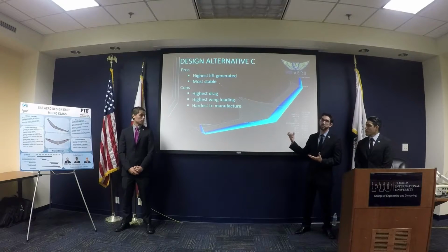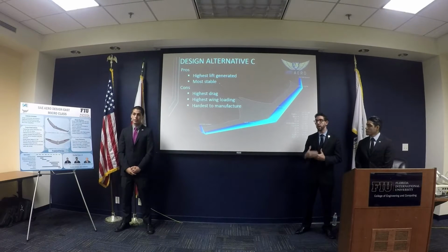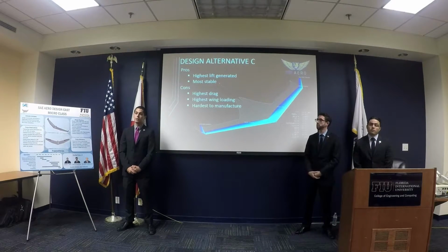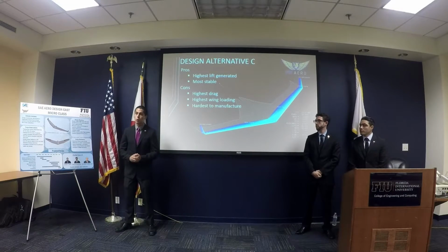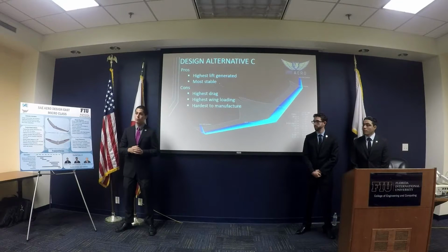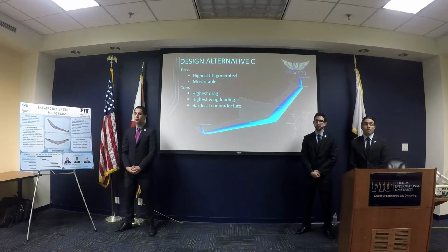Alongside playing with the center of mass, like I said, there are a lot of things that go into this. The flying wing will be unstable at most of the ranges. It has a very small stability margin. It can only fly at certain angles. It cannot do aerobatics. It's a very mission-specific aircraft. To elaborate on what he says, the competition does have certain rules. We're limited to a 60-second flight time. We also have a certain track, a circuit, where we go straight, do 2 banks, come back around, and do 2 banks. So we are not planning on doing any sort of rolls or acrobatic performance. It's very mission specific.